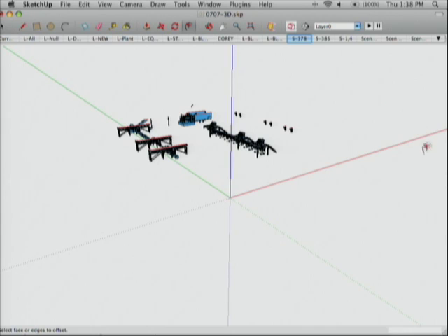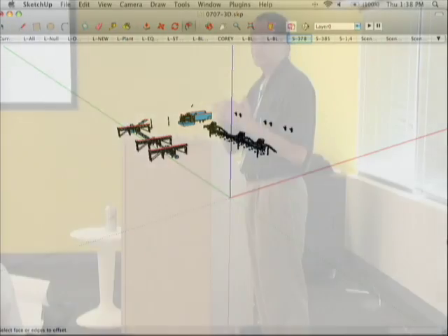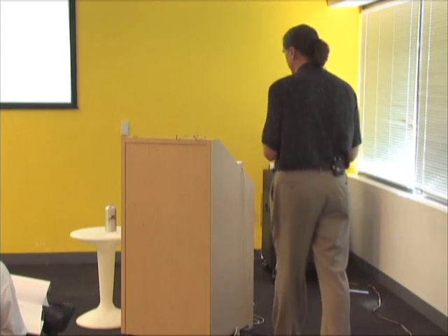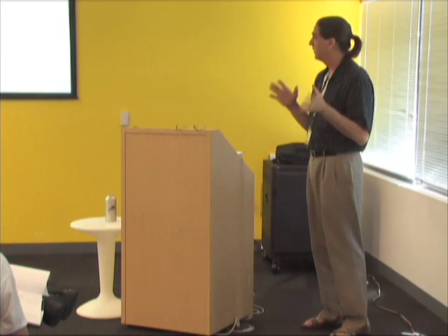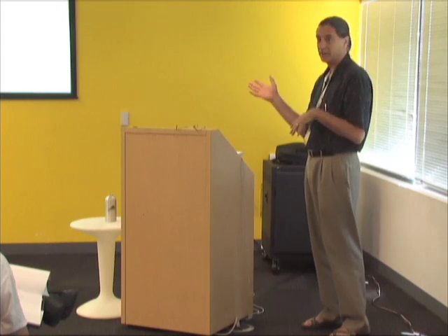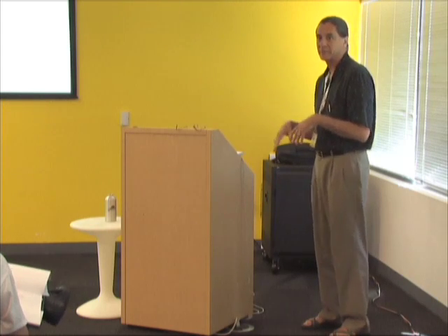The other thing I hope you notice is I've turned off transitions. The 142 meg model I opened had transitions turned on. I almost always turn that off because it's a real problem. I never use shadows unless I'm going to take a picture. Like somebody asked me what the shadows of a building do. I get it all set up because when you turn on shadows on a model like this, you're just going to wait for a long time.